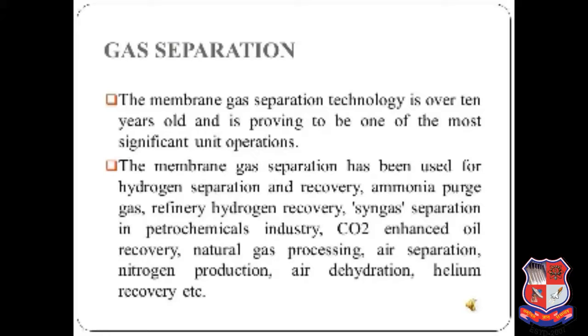The vapor and gas are separated due to their different solubility and diffusivity in the polymers. The permeability or permeation coefficient of such a non-porous membrane can generally be expressed as the solubility of the gas in the membrane polymer multiplied by the diffusivity of the gas in the polymer. So that is called the solution diffusion model. So this gas separation method is based on the solution diffusion model.